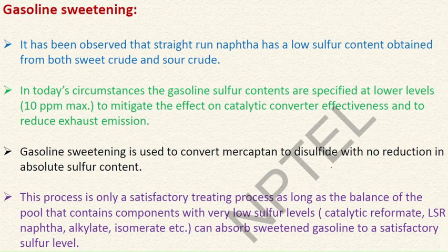Coming on to gasoline sweetening. So what is sweetening? As I told you earlier as well, sweetening is basically not reducing the sulfur content, but dealing with the presence of sulfur impurities in a petroleum cut or distillate cut, or here we can say gasoline. If mercaptans are present in a gasoline cut, it gives out a foul smell. So these mercaptans provide a foul smell to the distillate cut.